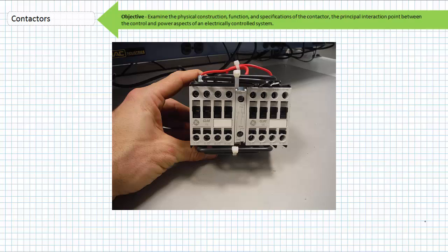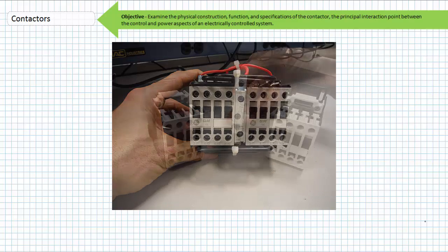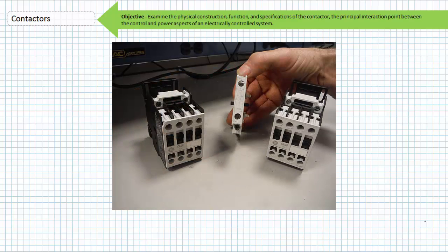Such a heinous condition could be prevented by two contactors in close proximity with a mechanical interlock between them. The movement of the forward plunger inserts a lever into the path of the reverse, and in the event the reverse coil is simultaneously energized, the lever prevents the movement of the reverse plunger. When the coil of one contactor has been pulled in, the mechanical interlock simply prevents the other contactor's plunger from moving, like sticking a foot in the door.